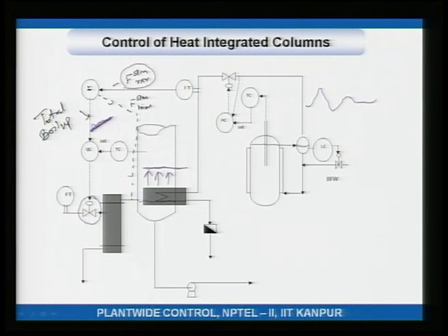If the steam from the reactor is increasing, steam into the trim reboiler will be decreased, and therefore, variability in the boil up will be much reduced. Because the variability in the boil up is much reduced, temperature is relatively constant. Okay. So, in this scheme, the product purity control or the split will be controlled better, more tightly. Okay. That's it for today.